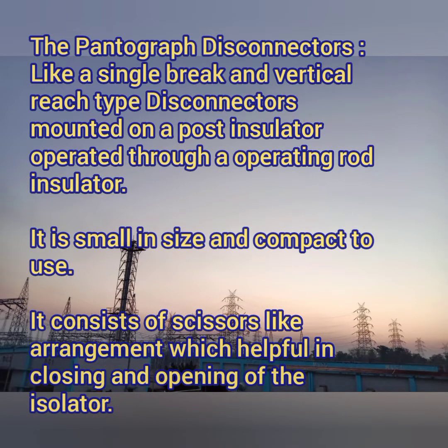Then coming to the pantographic disconnectors or isolators. Like a single break, it is a vertical reach type of disconnector which is mounted on post insulators, operated through a rotating or operating rod insulator. Its size is very compact, and it consists of a scissor-like arrangement which is helpful for opening and closing of the isolator.